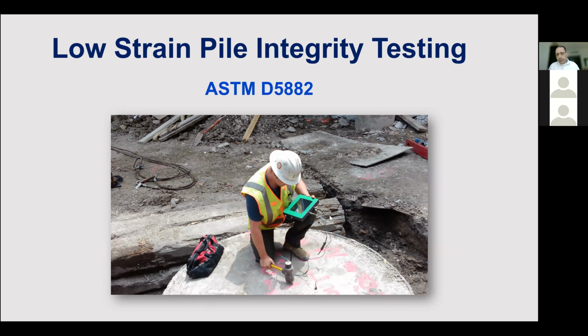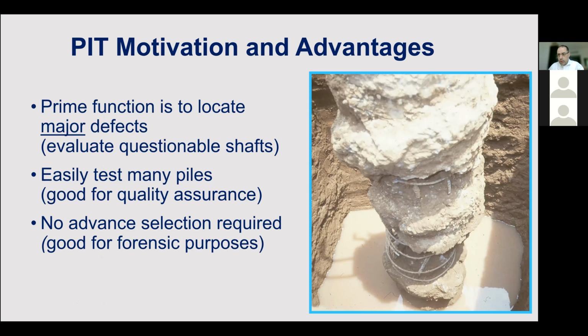Low strain integrity testing is a method described in ASTM D5882, and its prime function is to catch major defects or evaluate questionable shafts.